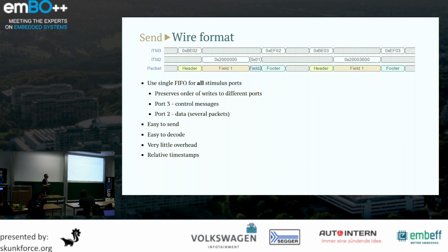Given the ITM capabilities, we can define a wire format for our trace events, so how we will serialize the trace events captured from trace hooks from FreeRTOS. We take advantage of this shared FIFO for all ports, and we can use, for example, port 3 to send control messages indicating event ID and start and stop of the event, and port 2 to send data. So we can